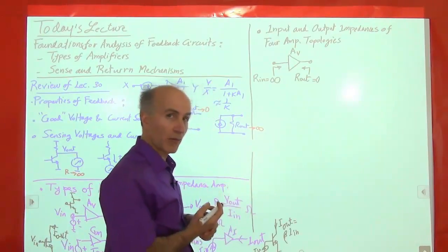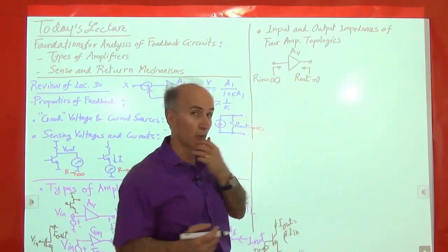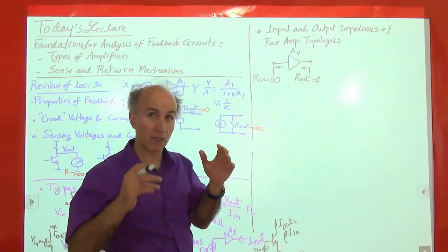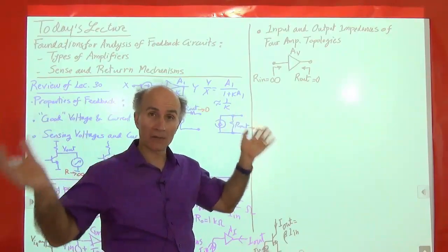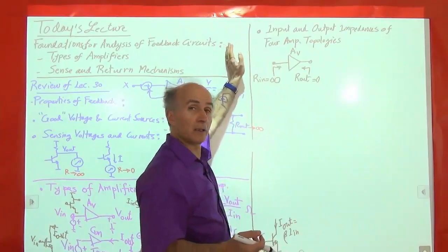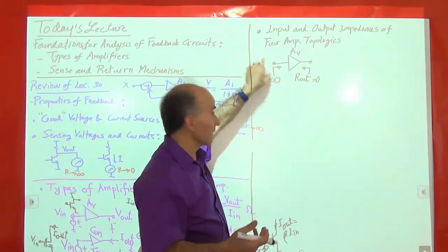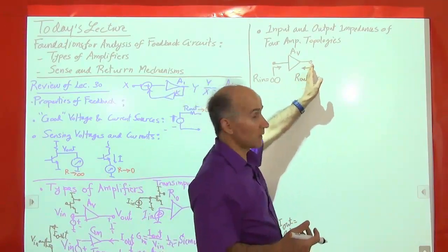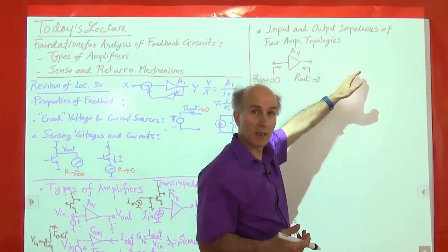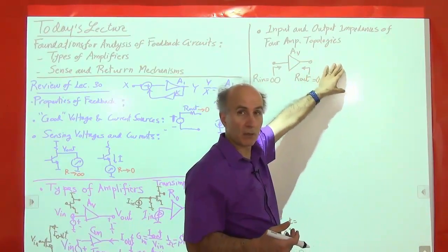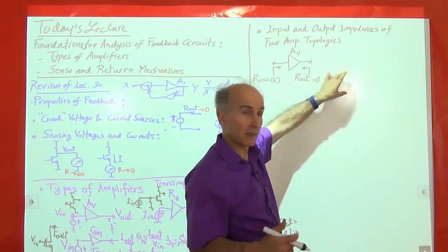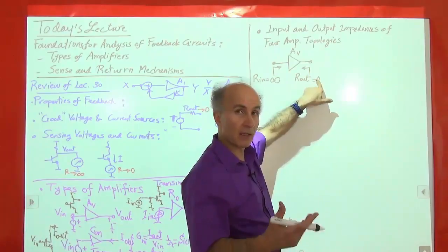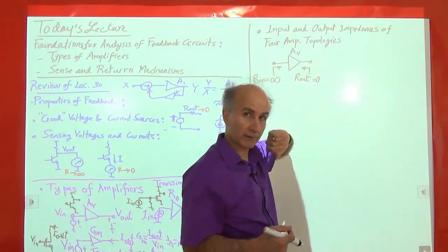All right. So that's the model that we have for a circuit that senses a voltage and generates a voltage. In the ideal case, it interfaces very easily with the outside world. It interfaces on this side with the preceding circuit easily because it doesn't load the preceding circuit. And on the other side, it interfaces with another load very easily because it can drive any load. Even if the load is 10 ohms or 1 ohm or 5 ohms, it can still drive it because the output resistance is very small. You can think of this as a Thevenin equivalent resistance for this circuit.